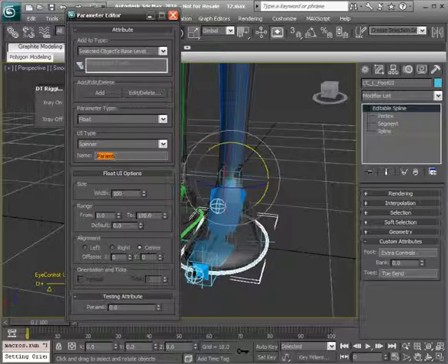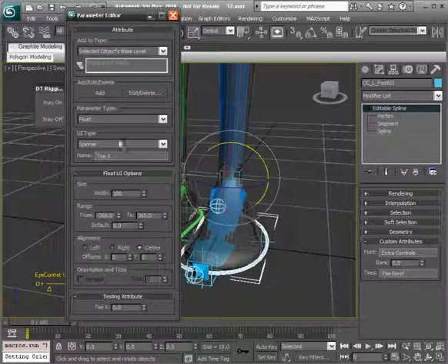The first control is going to be for the X direction for the toe, so we'll simply label this toe X. We don't have to have a huge range for our from and to, or for our min and max. So for the from, I'm going to just put in -360. For the to, +360. The width we could also change to 100, what we've been using before, and then choose add.